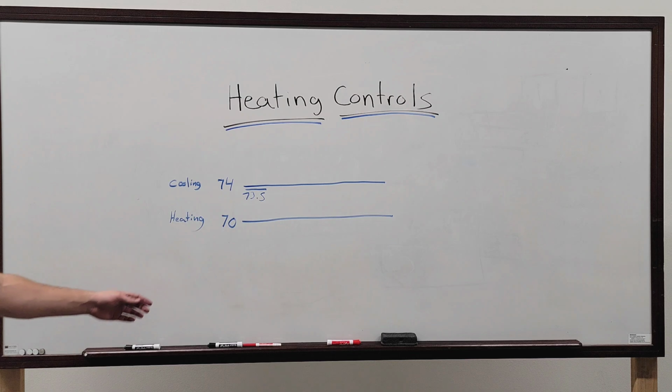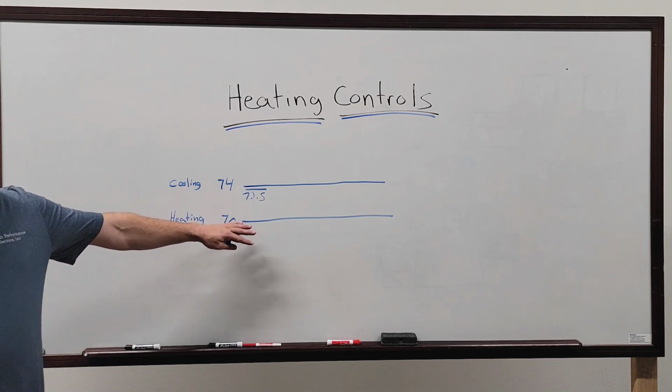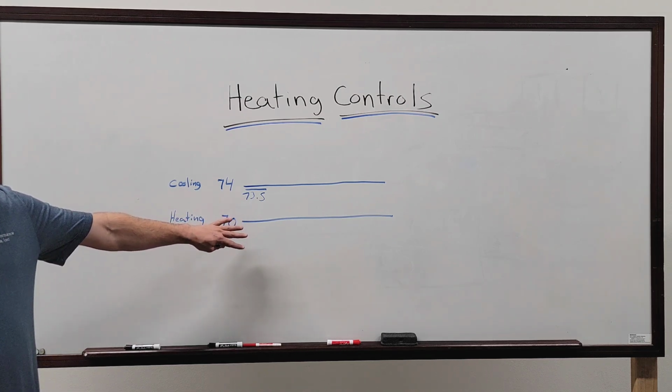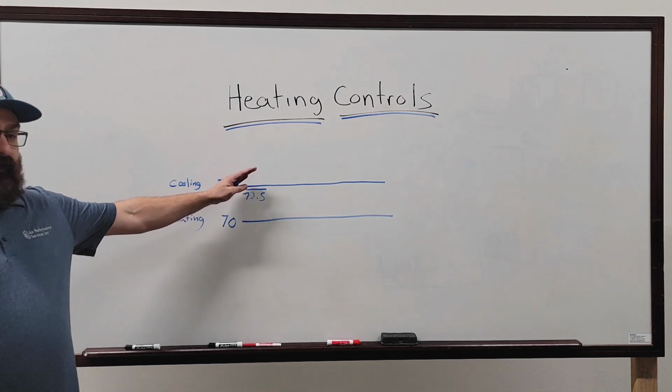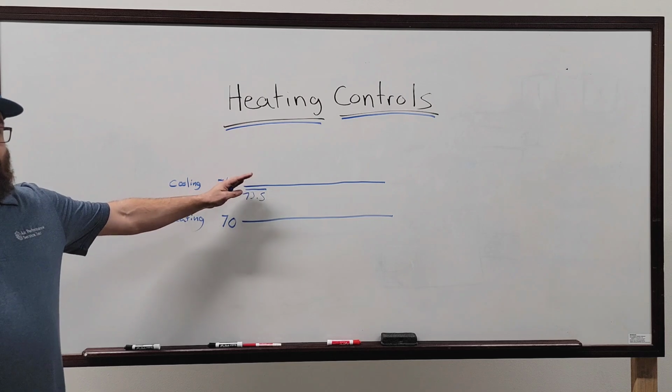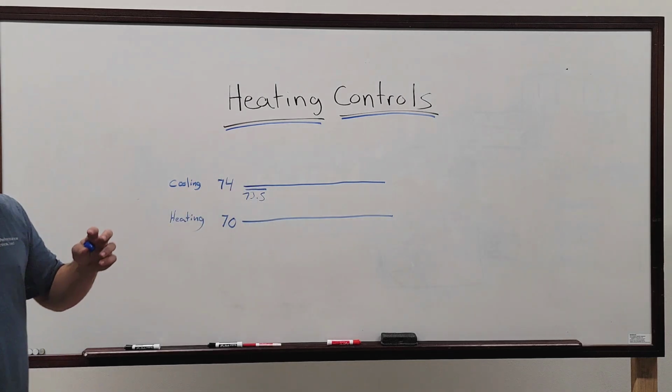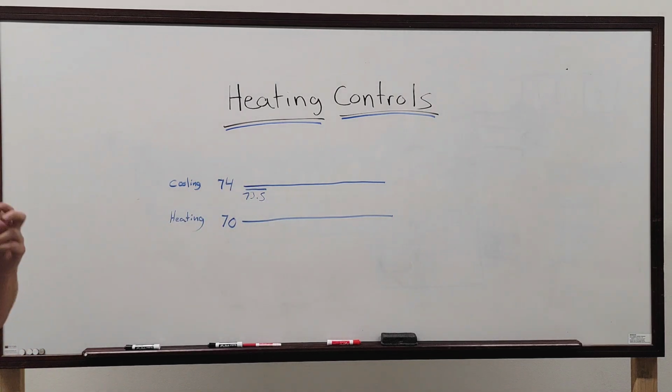Well, it's in heat mode because it had gotten below or close enough to 70 to trigger a toggle in the mode, and it has not gotten hot enough to trigger back to cooling. So it's satisfied. It just doesn't show satisfied. Honeywell's real bad about this. Johnson has a satisfied mode, right? This tech can say satisfied. Honeywell does not have satisfied. Honeywell is heating or cooling or off.